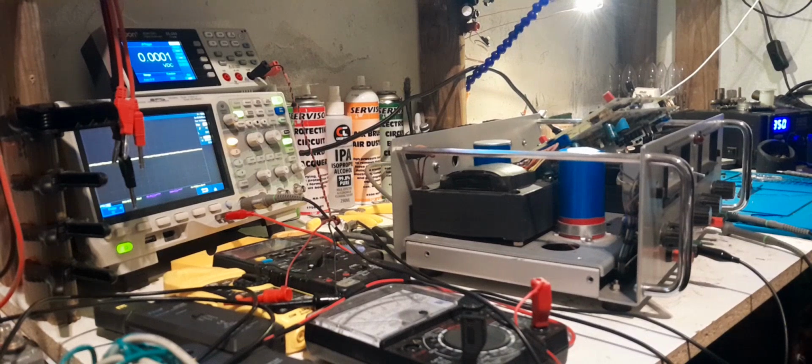I guess the person that asked me this already knows why, but for other people who might be wanting to learn probing techniques, the reason for this is basically if you just connect a scope probe anywhere across anything, say I was looking at a reference and I put the ground on the cathode and the tip on the anode, well, my probe would be looking at the power supply rail for starters, and second, the ground could be doing a number of things to the cathode.